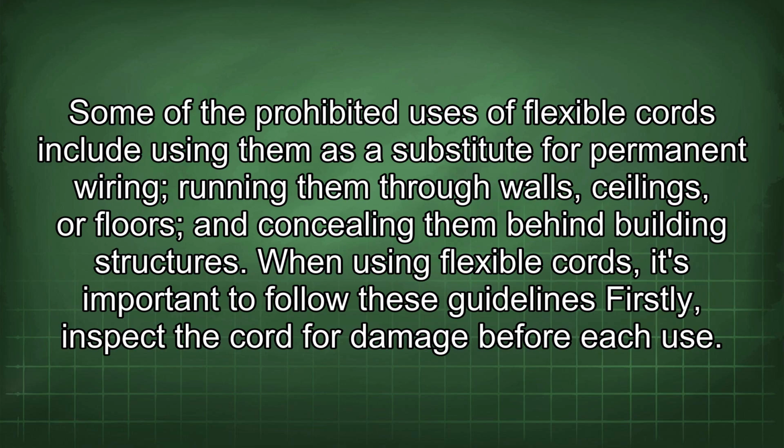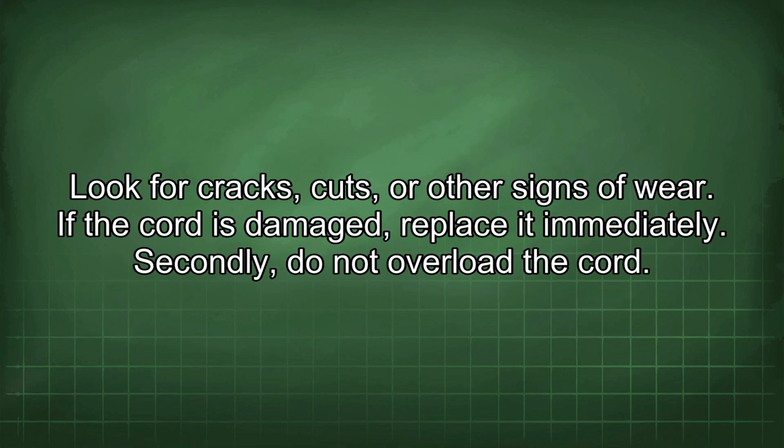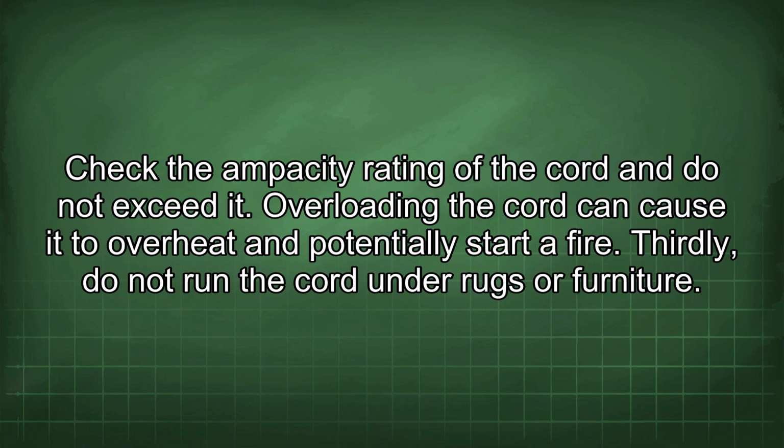When using flexible cords, it's important to follow these guidelines. Firstly, inspect the cord for damage before each use. Look for cracks, cuts, or other signs of wear. If the cord is damaged, replace it immediately. Secondly, do not overload the cord. Check the ampacity rating of the cord and do not exceed it. Overloading the cord can cause it to overheat and potentially start a fire.